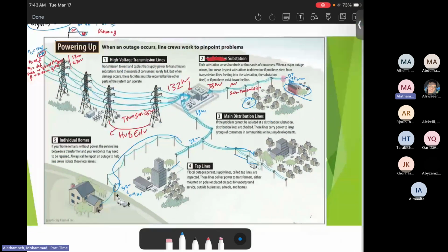Then you can have a clue about the transmission and distribution as we see here. You can imagine those poles are medium voltage poles. They can be either 33 or 11 kilovolts. Most likely inside the downtowns or inside the cities, there will be 11 kilovolt and most likely underground cables. But outside of the cities, you will see maybe 33, very few 66. It's very few, no longer in service, I think no longer in production. But you will see the vast majority are 33 kilovolts and very rare 11 kilovolts.